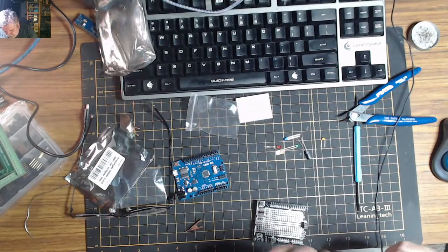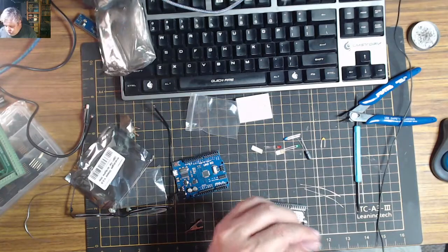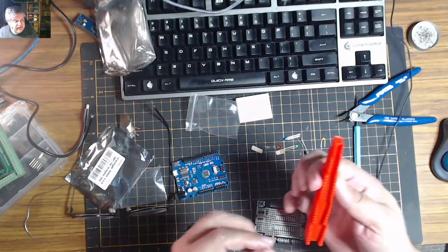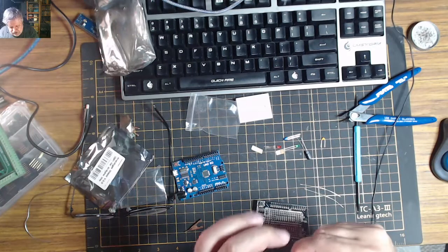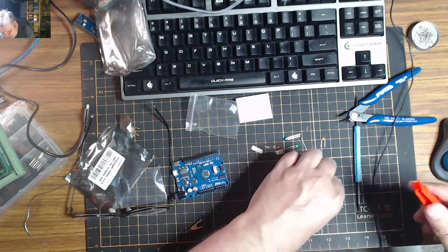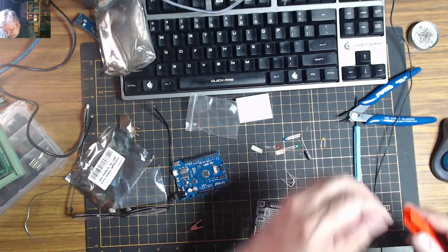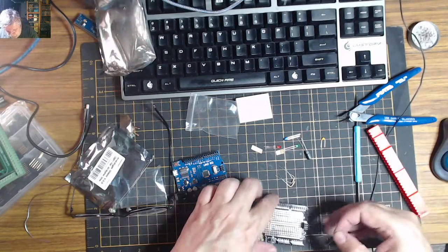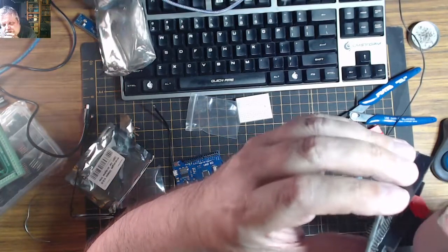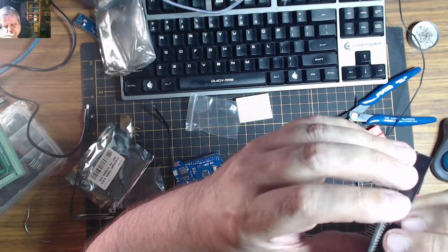Okay, so stock resistors. Now, a little funky tool, expensive as hell, but handy as hell. This guy here. It's for bending legs. You put it in here, you go like that. There we go, all legs bent. So we put in and we try to orient all the resistors in the same direction.